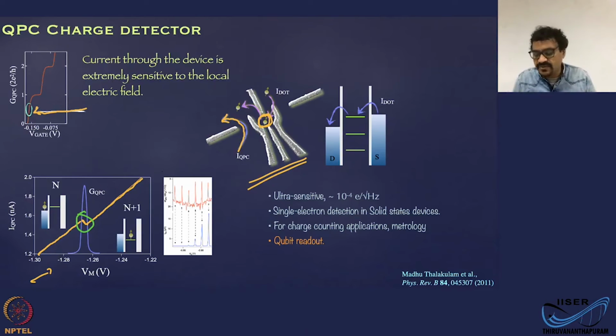So just to understand the process a little bit more clearly, when you sweep the voltage, this is Vm, whatever is labeled there, you are going to push this electron out because you are creating a negative electric field which pushes the electron, or you are basically increasing the energy of the electron states inside the trap, inside the dot. That is what is represented here. So you will push these levels up, and whichever electron was here will jump out. Of course, then another electron will jump in once it jumps out.